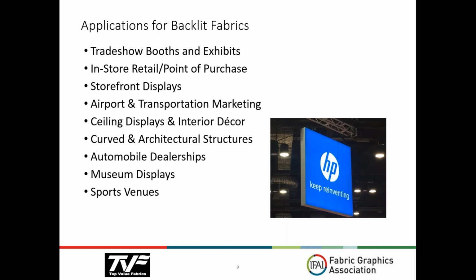Any coated fabric or any fabric for that nature, you don't want to scratch with a sharp object because you're actually disturbing the fiber on the surface and can create defects. What we typically refer to as crock fastness, which means rubbing, which can occur when you handle the fabric or sew the silicone edge on.